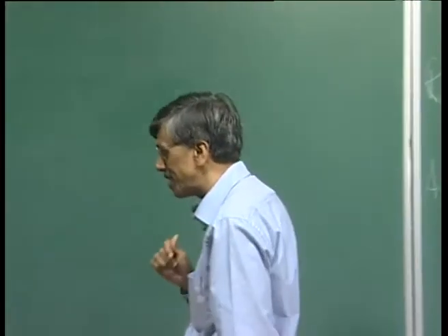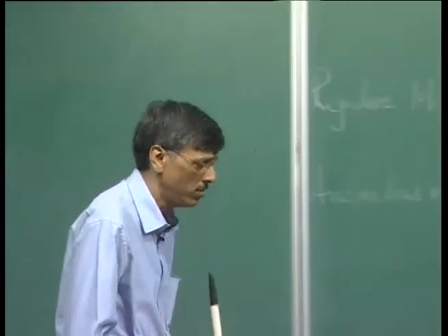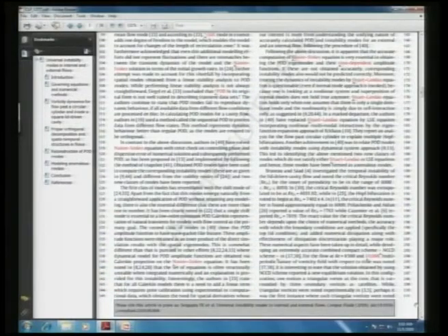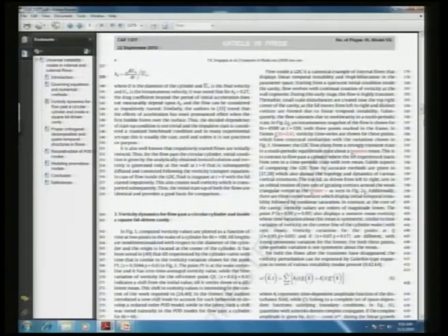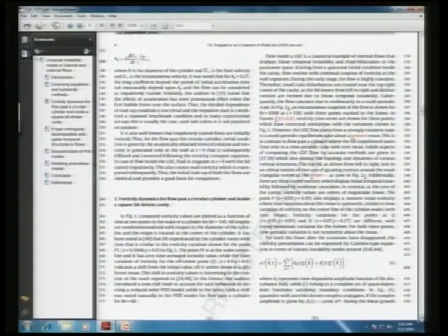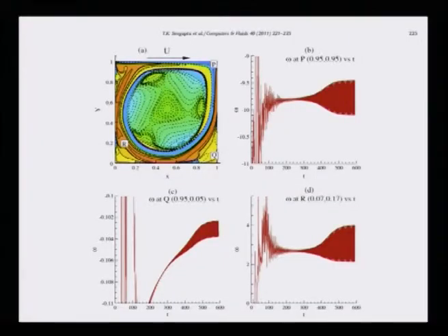So, what we have done, we have undertaken to study the same thing for an internal flow. This is basically a lid driven cavity problem. A lid driven cavity problem is as it is shown here. What we are going to show you here is a picture that will demonstrate what is going to happen. We go through the same process of solving the Navier-Stokes equation and get those solutions, then obtain the instantaneous flow, then you obtain the mean flow, and then what we are going to do is basically calculate the disturbance flow, and once you have the disturbance flow, you obtain those Galerkin projections that we are seeing, and this is what your driven cavity program is.